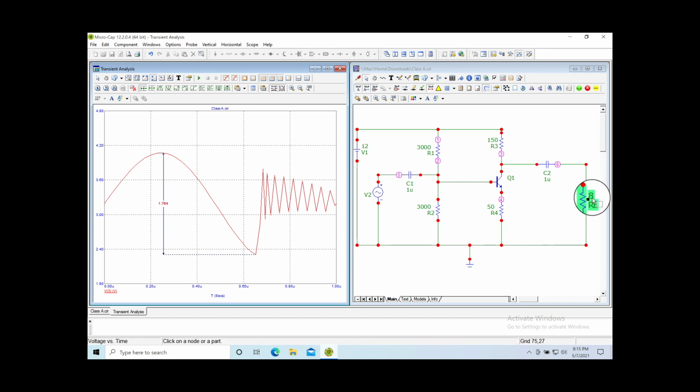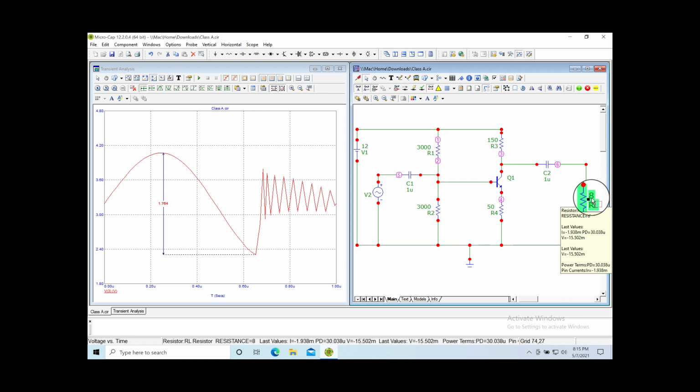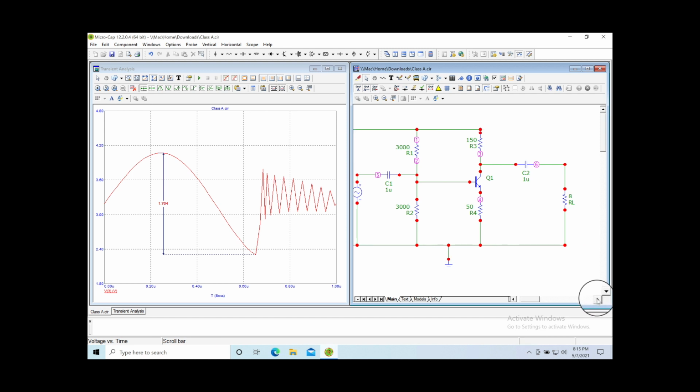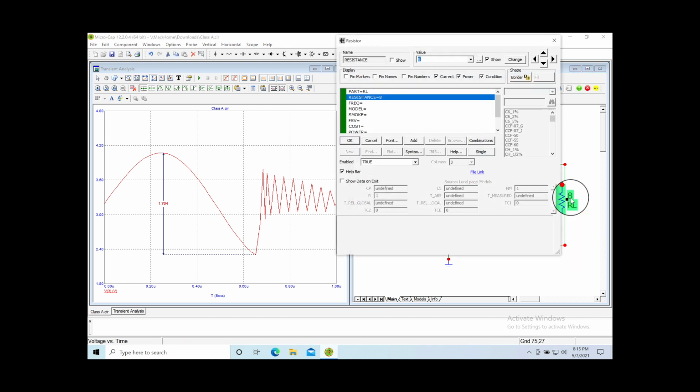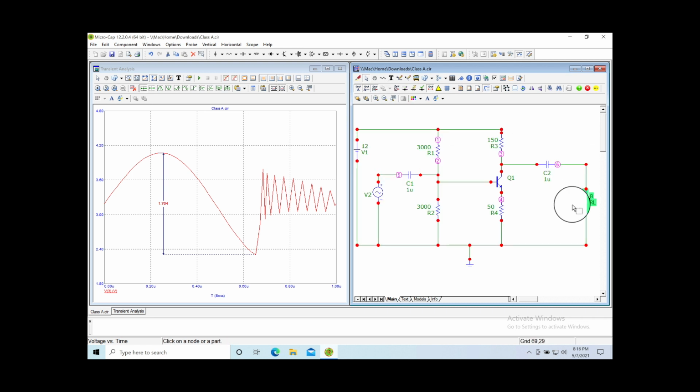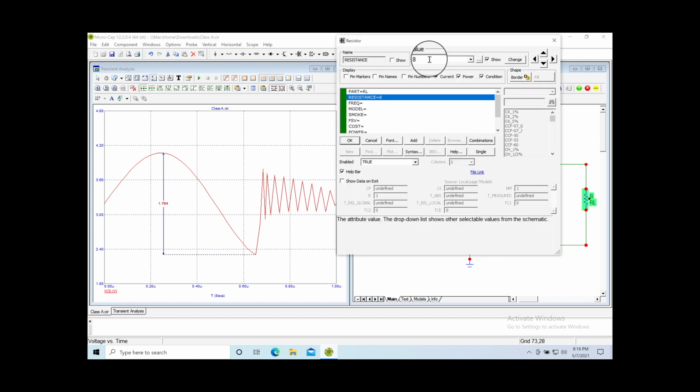So let's come over here and just change. Whoops. That's what happens when you click on the resistor, the RL. I want to click on the 8. I have to kind of hit this little button so I can click on this guy. All right, so let's click on the resistor here and come up here and make it 80 ohms. Well, I'm going to just change it to 100 ohms. Nice even round number, 100 ohms.